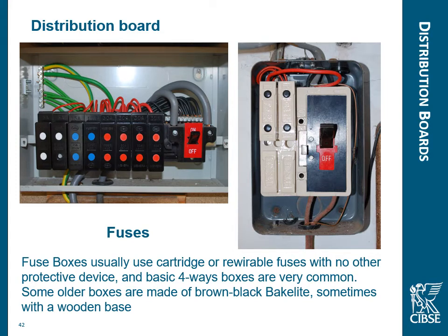Now, years ago, before we had circuit breakers, we had fuses. Now, fuses didn't give us the same sort of protection as circuit breakers. But one good thing about fuses, it made us think a bit more, because it's very easy to reset circuit breakers, whereas we have to take the fuse out, rewire it, or put a new cartridge fuse in, or if you've not got one, go down the shop and buy one, put wire in it and stuff like that. We think about the fault rather than just keep resetting it, because with circuit breakers, we tend to just keep resetting it, thinking the fault might go away there.